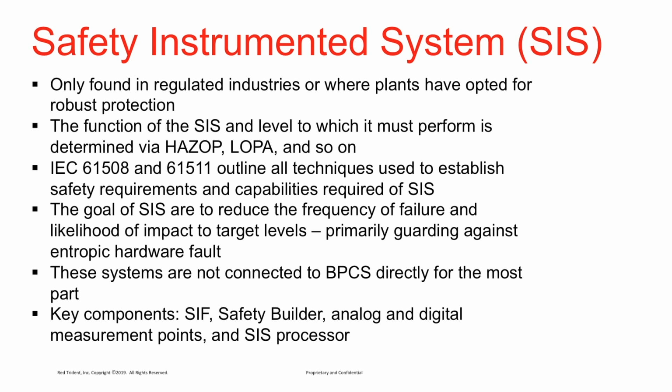And I run into a lot of places that put the safety builder and the engineering workstation on the same computer. You are giving the keys of the kingdom to somebody. Now, they have the ability to modify the safety instrumented function, and they have the ability to modify the process itself. Now, the interesting part, though, too, is I remind people with the safety systems, all you have to do is disable its functionality or give it a new tolerance, and then all you have to do is just wait. You don't actually have to hack the process. You just have to wait for an unsafe condition to occur.